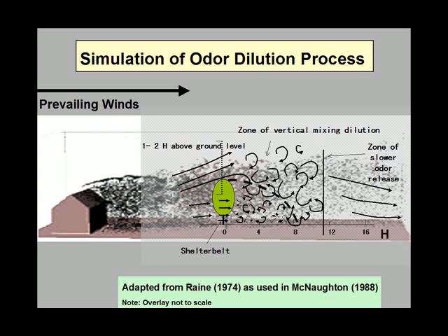And so we've got this high turbulent zone right here where what's being emitted from this building comes up and over, and it gets sort of caught up in there. And it allows for a much slower release of these particulates back into the downwind airstream. And so this is really where we're getting a lot of this dilution effect, this dispersion effect as well. We're also getting a lot of particulates actually being physically caught and held at the shelter belt surface itself.